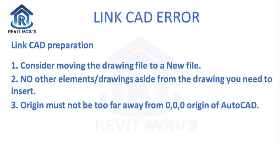And if you don't do number 1, you will be hesitating to do it because it might have some global coordinate system on your CAD file that may affect the other file that has a reference on it, or the other users that are using this CAD file as an external reference. So if you manage to do the first one, step one, then you will have the confidence to move your CAD file to the 0,0 origin.